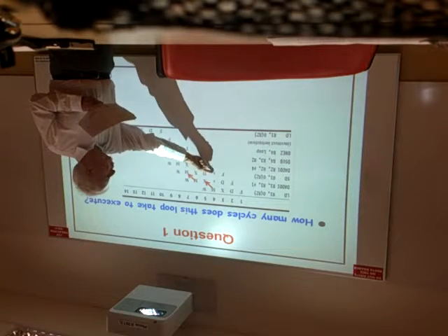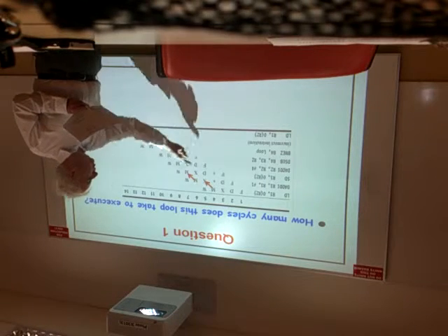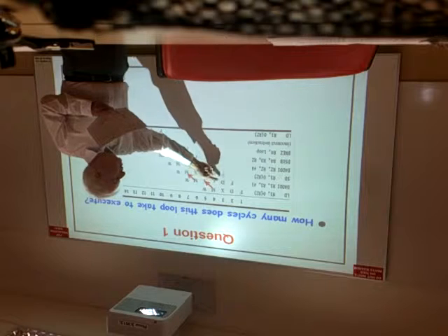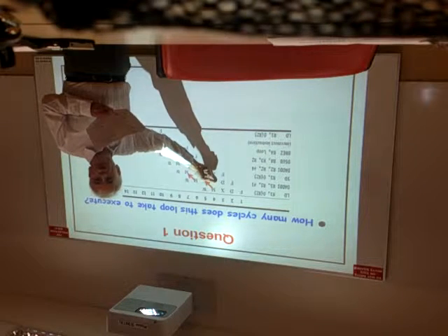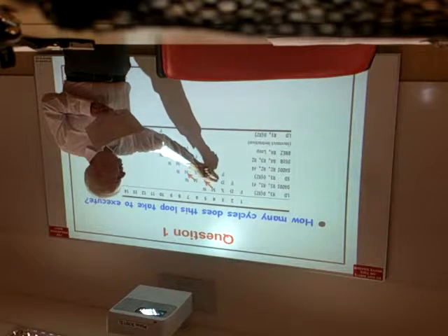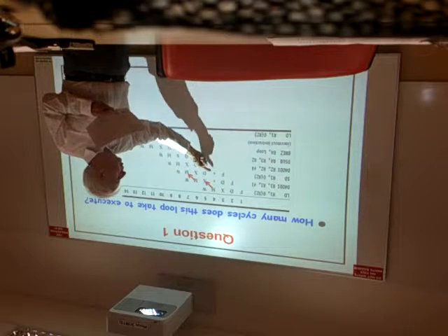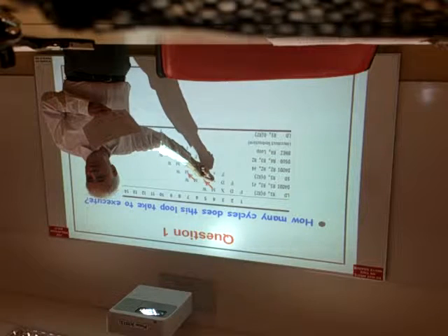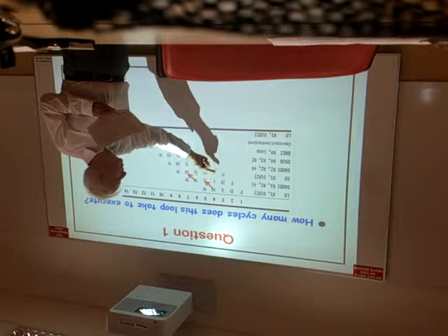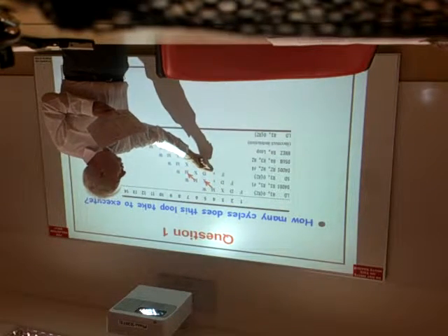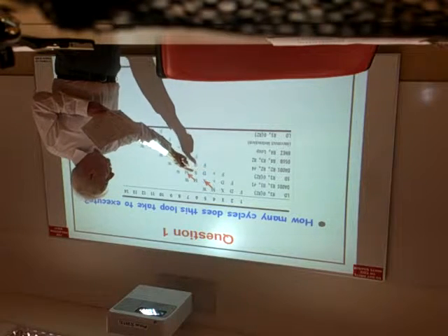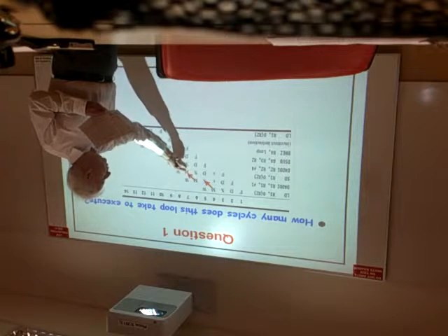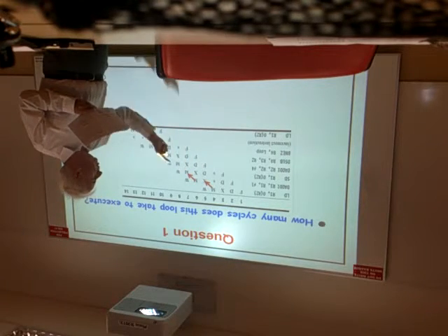However, we still need a stall here because in the previous instruction we have a stall, and this instruction, because we've stalled, is still in its decode stage, so we can't try to decode this instruction until the previous instruction has finished decoding. Okay, so we have a stall here, and we forward the value of R1 for the M stage of the instruction.